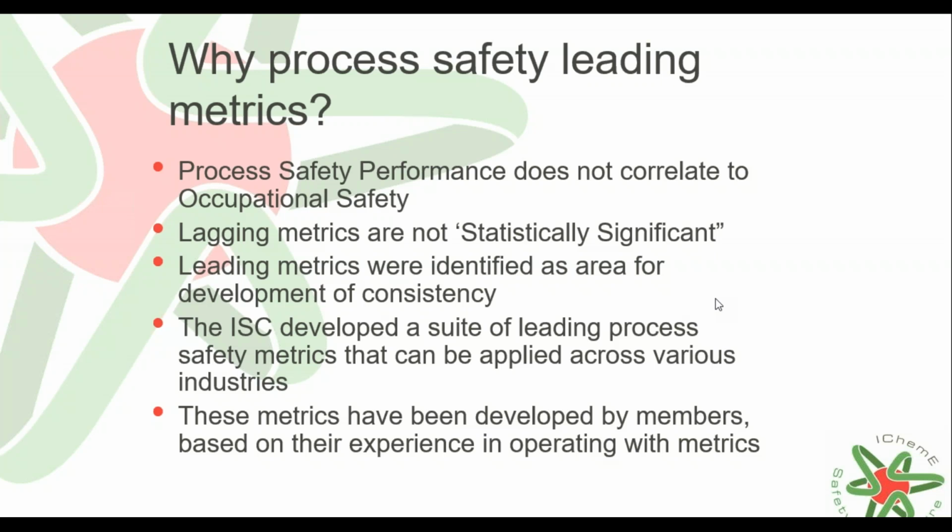If it's something that's maybe a little bit more benign or non-flammable, then that might be able to be done. But I can tell you in our particular situation, it was a gas plant, so we were having gas releases of a reasonable pressure, up around 60-80 bar. So we were getting quite significant gas clouds as a result of those trunnion leaks.